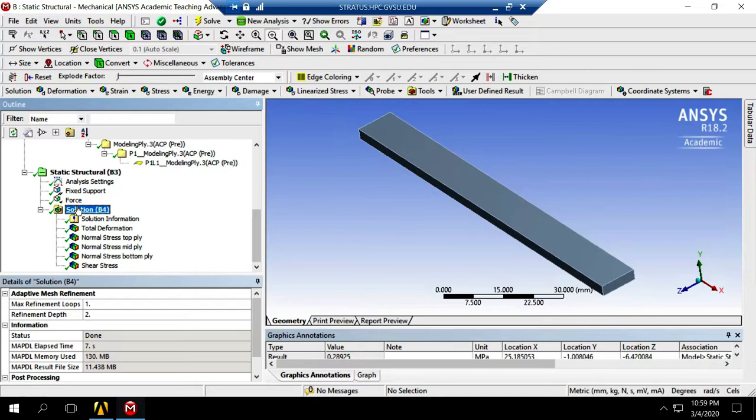It just says whenever sigma L reaches sigma LU, which is something we studied in chapter 3. In chapter 3 we learned how to find maximum normal stress in longitudinal direction, and in transverse direction also we studied that. And tau LT U also is something we can find. So this theory says once any of these reaches their ultimate values, we have failure.